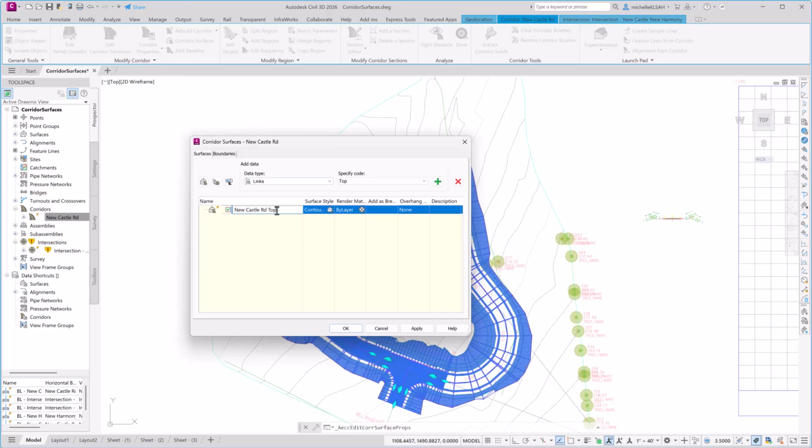going to look when everything is done, and I'll create a second one for my datum surface to indicate how it's going to look before I start adding concrete and pavement, and so that my grading operators know how deep to grade before all that other material comes in.